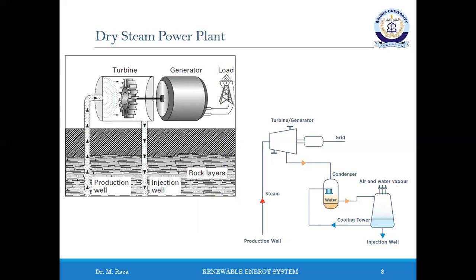This type of system is ideal for vapor dominated resources where steam production is not contaminated with liquid. The system configuration is essentially the same as the conventional fossil fueled steam power plant. The reservoir produces superheated dry steam coming out of the ground typically at 180 to 225 degrees Celsius and 4 to 8 megapascal pressure, reaching the surface at several hundred kilometers per hour, and if vented to the atmosphere, sounding like a jet engine at close proximity.